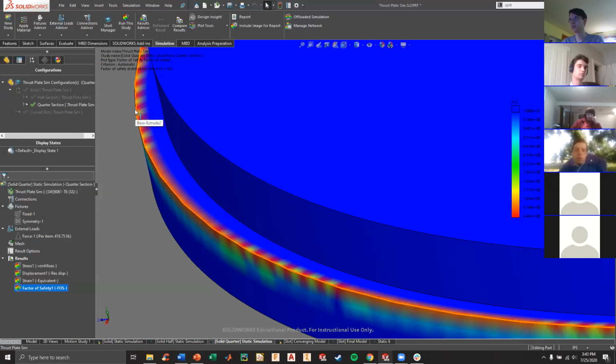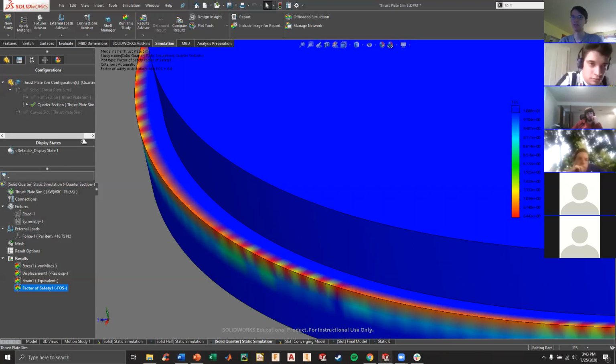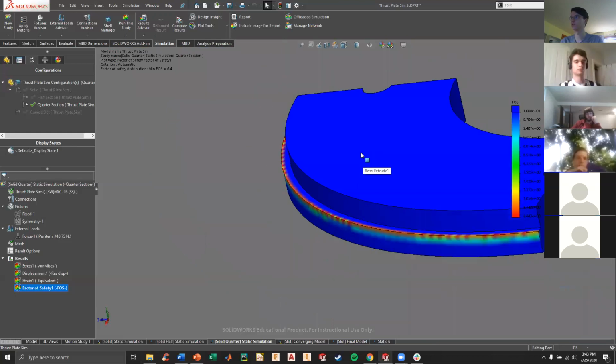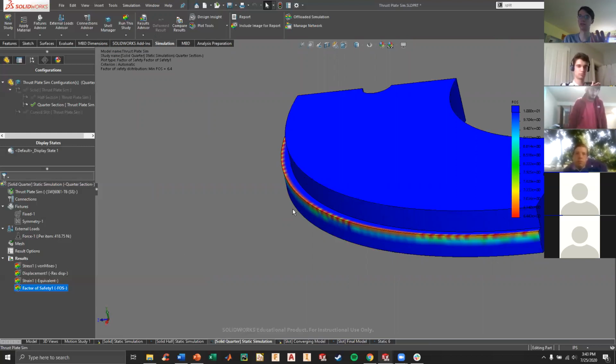And here, there are 2 options when you have a small area like this where all the stress is concentrated. It will either be a singularity, which is not good, means your model won't converge, or it will be a genuine stress concentration. So that might be like where you have a bolt going through and the bolt has a pretty low area of contact, but it's pulling really hard. So you'll get super high stresses there, but that makes sense. That is a genuine result.